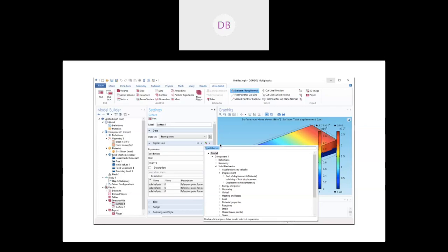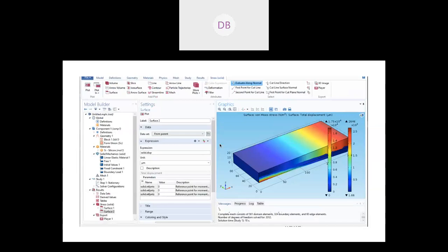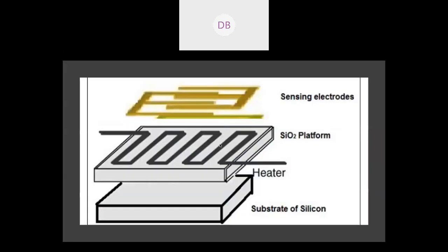So, as we started off designing a gas sensor, the major part in a gas sensor is a heater, a micro heater. For any gas sensing system, a micro heater plays a very important role, because we want the compound to be in a volatile state. And of course, our project is also the design of a micro cantilever for determining volatile organic compounds.